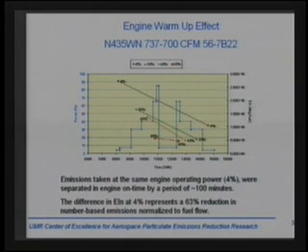And you can see at 4% here, and we're plotting time along here. It takes us all this time in seconds to get from the start of the test to the end of the test. There's a significant drop in the number-based emission index for that 4% condition, for the 2 points we got, which were the furthest apart in time in the study. This time interval here is about 100 minutes altogether. You can see this trend at other powers as well.